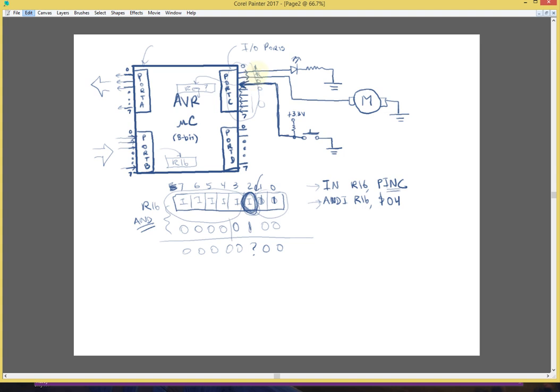When we're writing all 8 bits at once with the out instruction, how will we write these two that are the only two outputs but ignore the rest? We want to make sure we don't affect the rest. So you would set the bit pattern and just make sure that the remaining bits of all the registers are zeros. Okay, so if you wanted to turn them both on, then I would say LDI